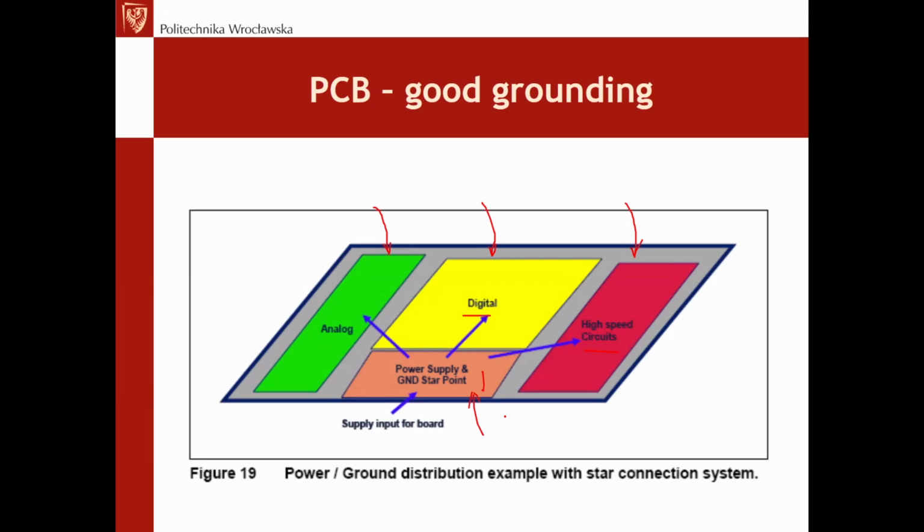because in this pale red, whatever the color, or orange box, we are to place the power supply itself, but also close to the power supply should be the high current components, here in this box. So four boxes, four areas where the components should be grouped, and this grouping greatly simplifies things. So it has two advantages.